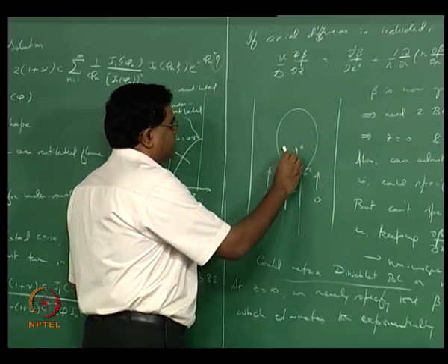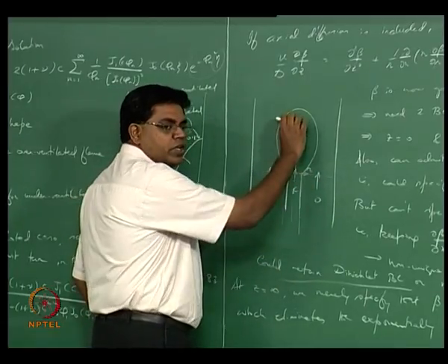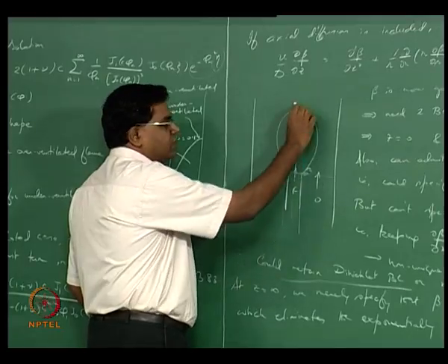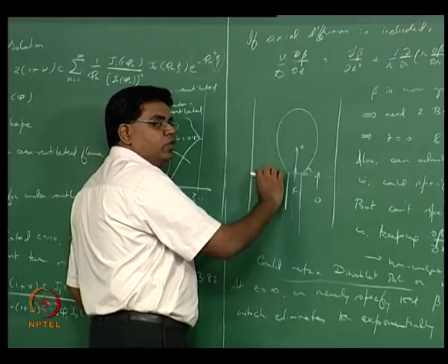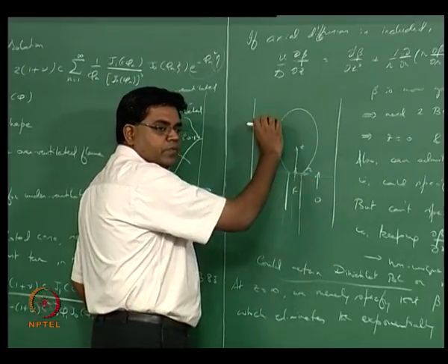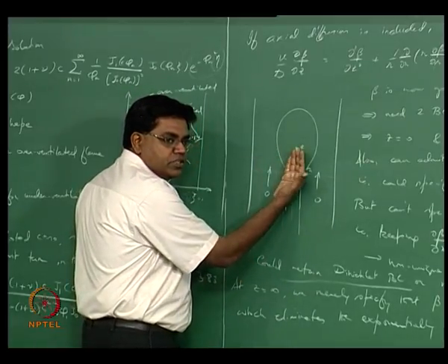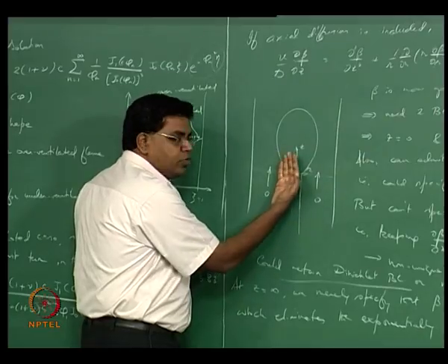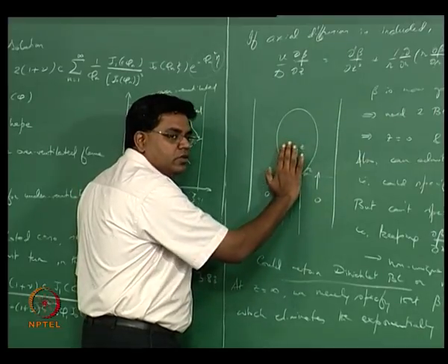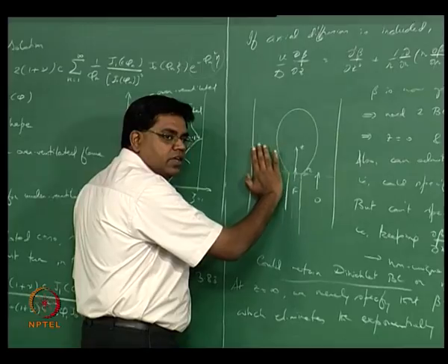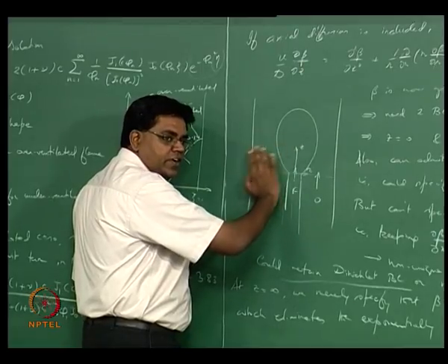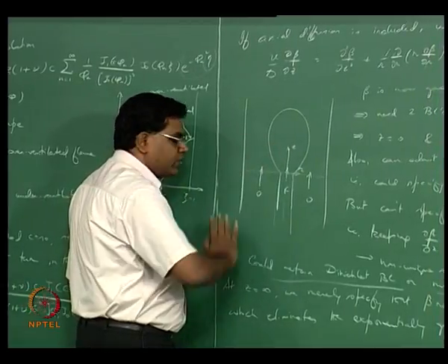This really means that you have a fuel rich region over here. This is the stoichiometric surface, this is the fuel lean region around, okay, and there is a progressive change in the mixture fraction from a pure fuel or more fuel in the middle progressively to stoichiometric and then fuel lean, okay. It's a varying region over there.